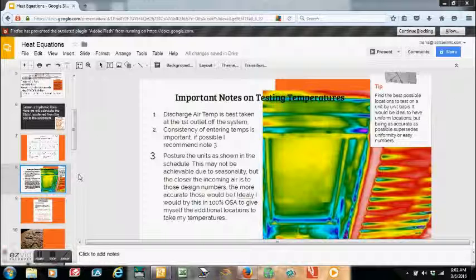In closing, I would treat these temps like you would a good traverse, as I just said, and your results will add value to a report. Get your measurements in the best locations possible. Verify the results make sense by cross-checking if possible or using common sense. Review this topic in your Blue Book or trusted resources to deepen your understanding.